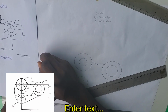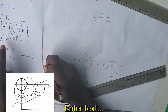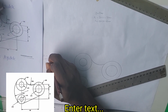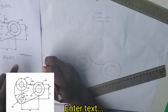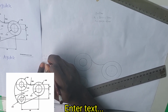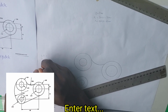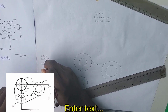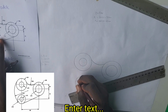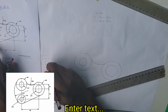So let's do the first one. For I1, the given radius is 70, minus the radius of this one, which is 27. 70 minus 27, it will give us what? Do the calculation very well. 10 minus 7, you have 3. 6 minus 2, you have 43 millimeters. Then for I2, we have the given radius 70 minus the other radius here, which is 20. That will give us 50 millimeters.